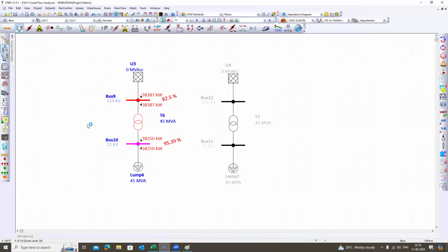Voltage, sir. See, in the solar plant there is an operation called night mode. Suppose your solar plant is connected to a large transmission line. When there is no solar power, your solar station will still be connected to the grid just to meet the auxiliary power requirement. At that time your voltage will be quite high because the line is almost unloaded, due to the Ferranti effect. Your receiving end voltage will be high.